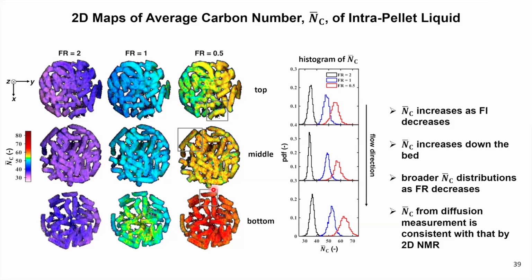where the liquid can go into? So they are filled with silicon carbide particles, which themselves have voids. Okay. So the liquid can go through. The silicon carbide particles are solid. They don't have voids, but there are voids between them. And so there's space for gas and liquid to flow through. Yeah, and I can see that most of it evaporates quickly, and so then you will have less density and less signal. I think most of it probably is liquid, so it's flowing down, but some of it will vaporize, some of it will be liquid, but most of it will flow through there. And it's probably the longer chains. I mean, what's really interesting, I think, is what's coming out the bottom is C28.